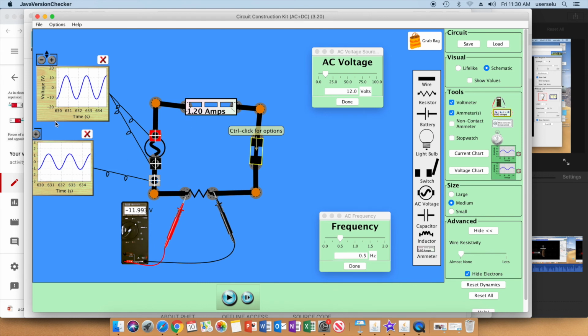Now, if I go to my charts, notice my voltage chart right at the origin is right now at minus 12. It's really a little bit below the 10, and it's hard to see here, again, because it's not really scaled to read very efficiently. But the current reading at the origin, on my current scale, is minus 1.2 when I'm at minus 12 volts.